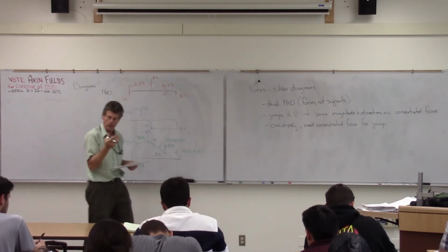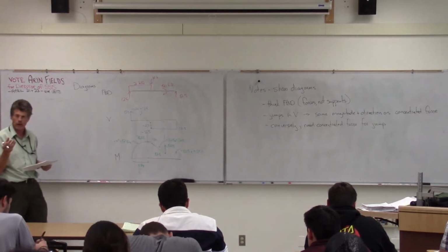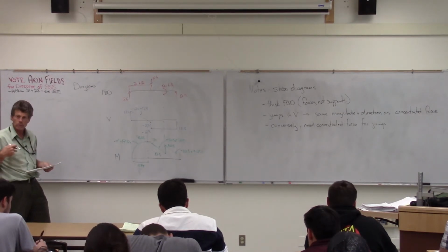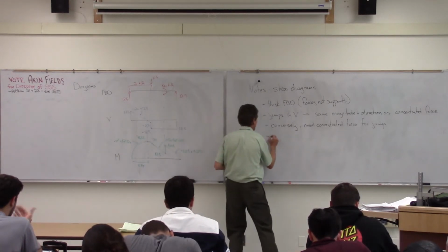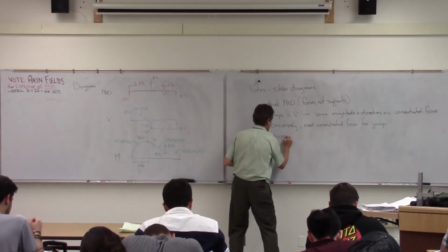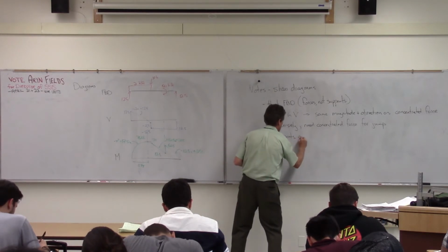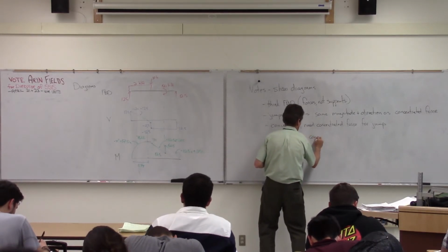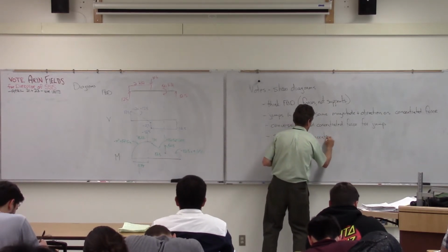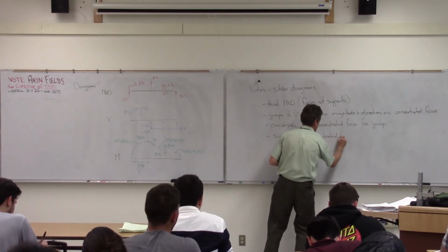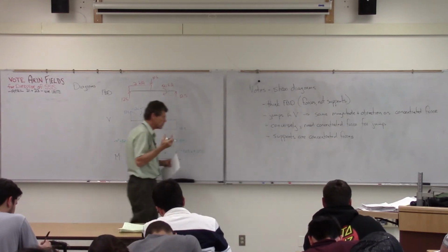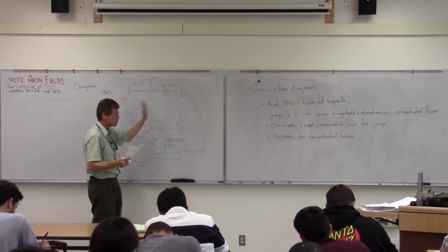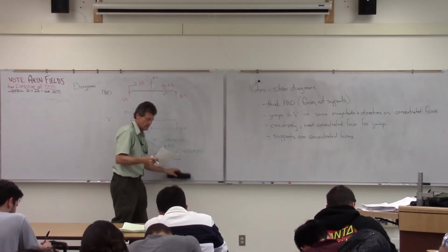So if you've got a jump in your diagram and you don't have a concentrated force there, go back and look at your equations. You've done something wrong. And again, going back to the fact that supports are concentrated forces. So the support could be out in the middle somewhere.